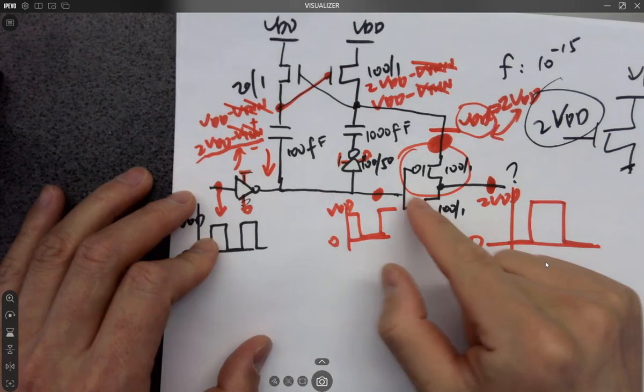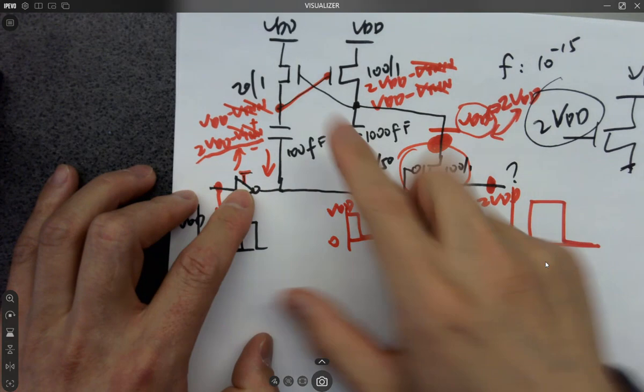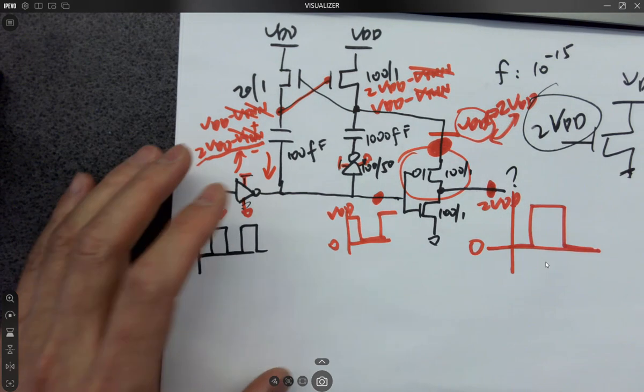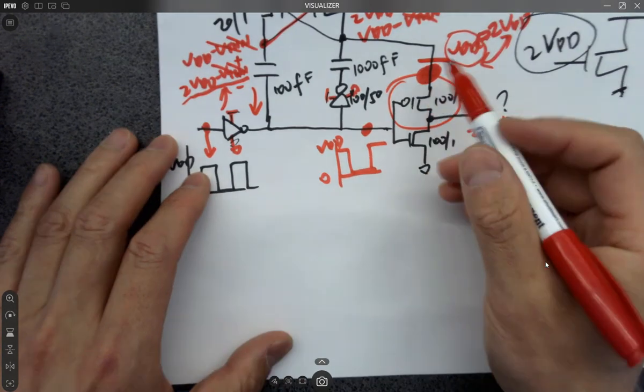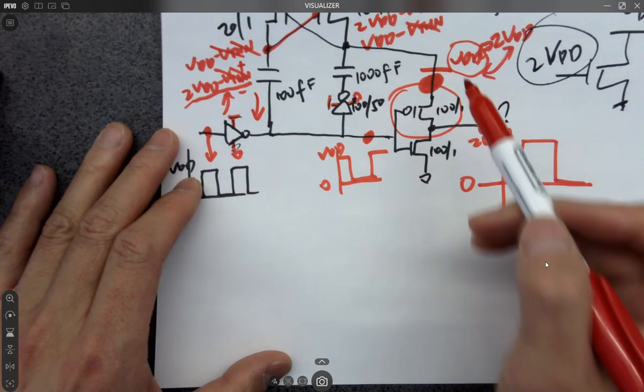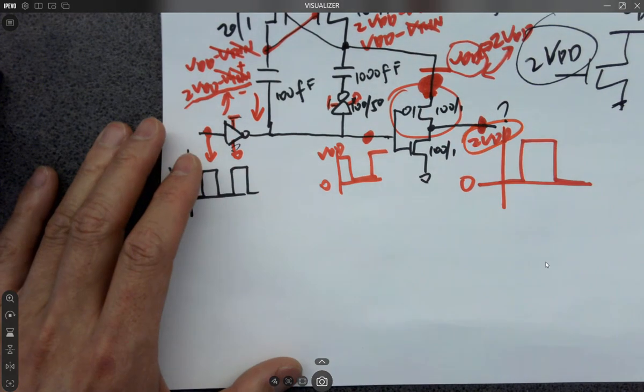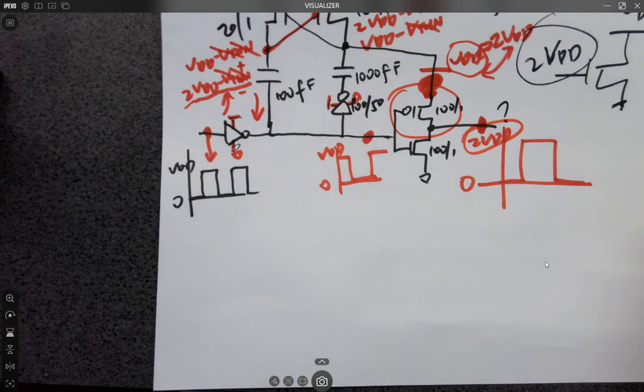Yes. Here, we have PMOSes here and here. Even though these are NMOSes, we have PMOSes anywhere else as well. So it's in all the places on the chip. So this PMOS is different because the source of the PMOS is 2 VDD instead of 1 VDD compared to other PMOSes. And why is that important to know?